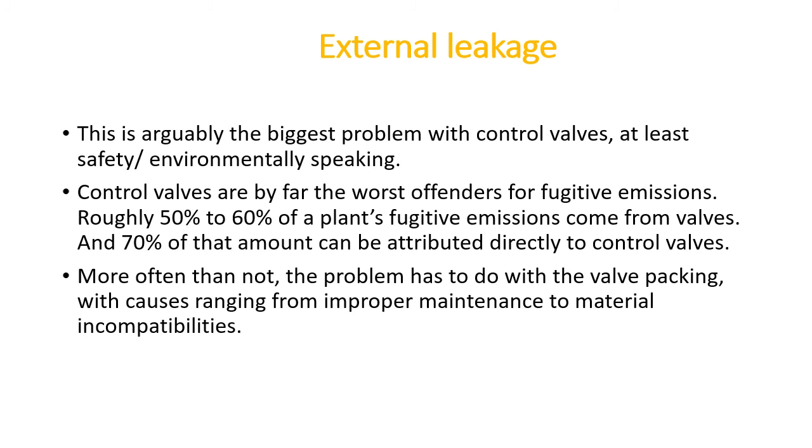Also, in some cases the service is very corrosive or very severe. In that case the packing has to be replaced after a certain interval. If not replaced within that interval, this may cause external leakage. In the worst cases, there is leakage from the body also, and this is a very severe condition. Leakage from the body may be a result of wrong selection of the material, or it may be due to cavitation or flashing issues.